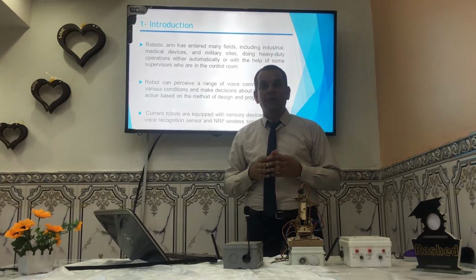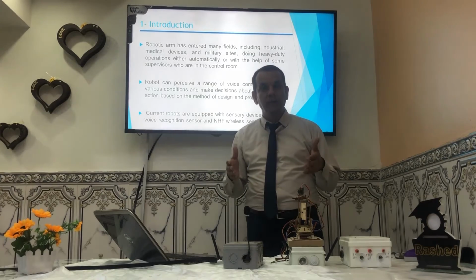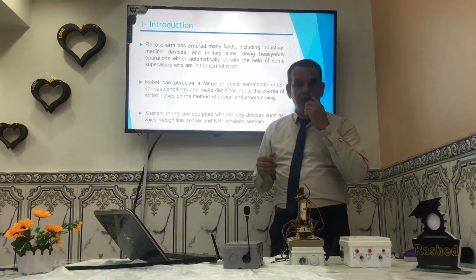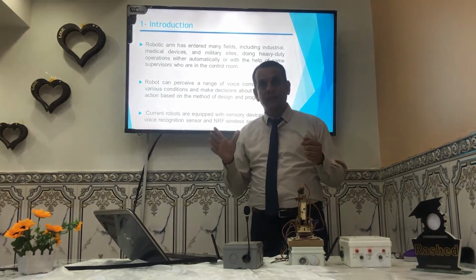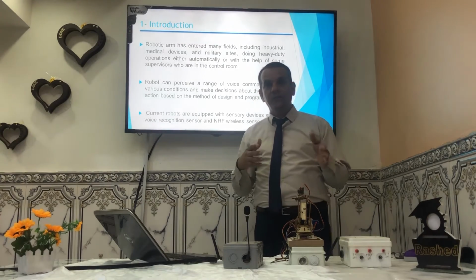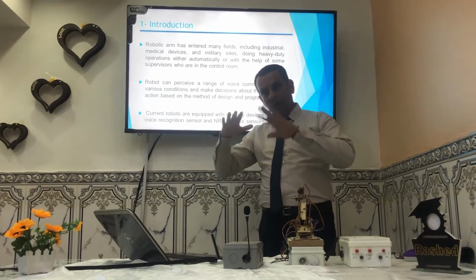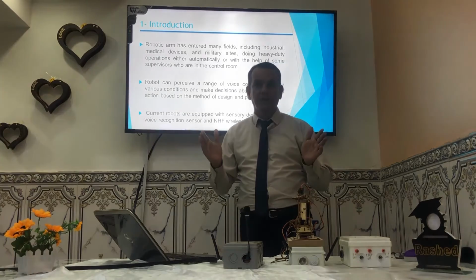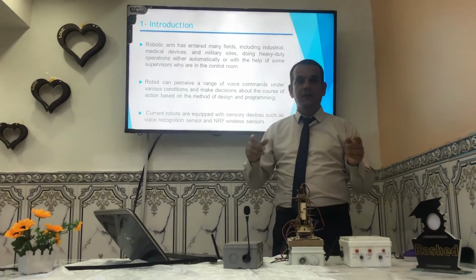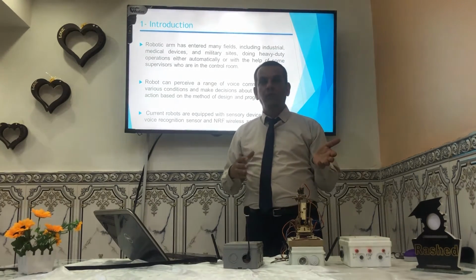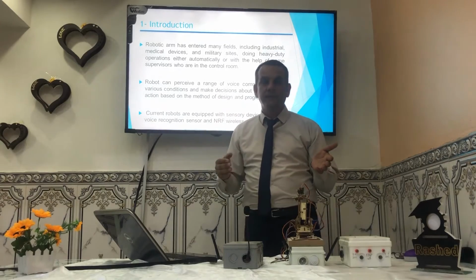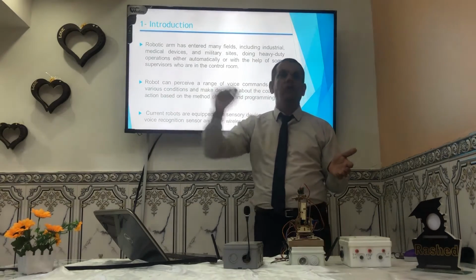The arm program has been trained by the voice sensor module on the voice commands in 5 groups. One group is "hello". It is the key to the whole robotic arm system. The others are base left and right, move up and down, forward and reverse, and the hand catch and open.